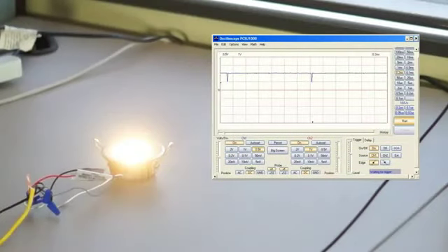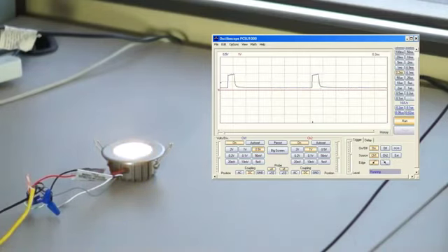Hopefully, PWM dimming will become more clear as you see it live. We have the oscilloscope now attached to the output of our PWM dimmer. We will now initiate a slow fade off. Notice that as the percentage of time that the voltage is applied decreases, the light grows dimmer. Remember that this is non-standard, and we've selected in software the inverse option.